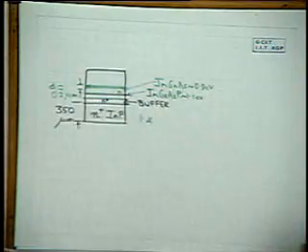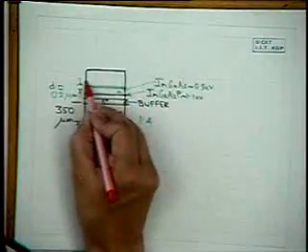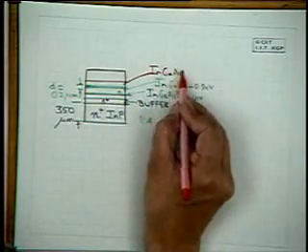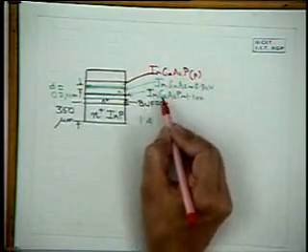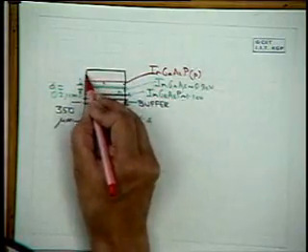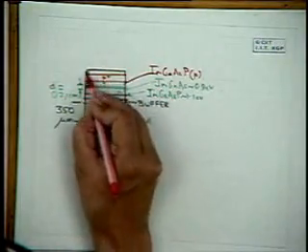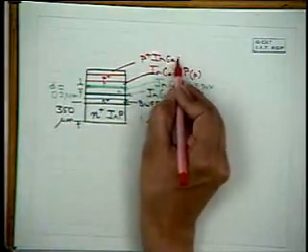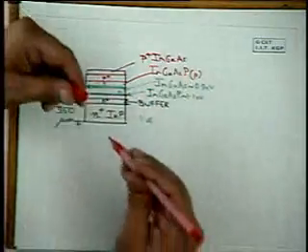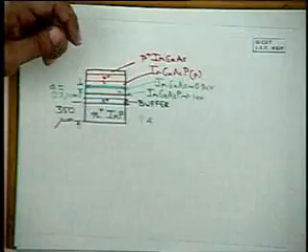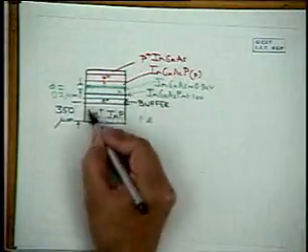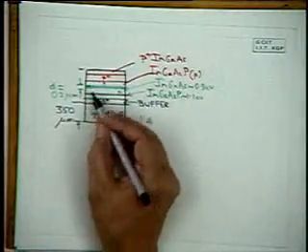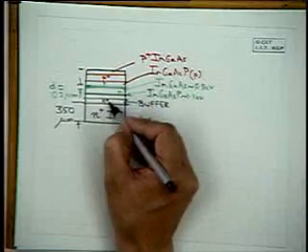The active layer is undoped, and then on the top we grow an indium gallium arsenide phosphide, P-type, with dopant typically zinc. Then we have a P plus, and the top layer could be a P plus indium gallium arsenide, which is low band gap, which will give you ohmic contacts. So although this dimension is rather exaggerated, this is 350 microns, the entire top dimension would be of the order of a few microns. This whole thing is of the order of a few microns at the most.